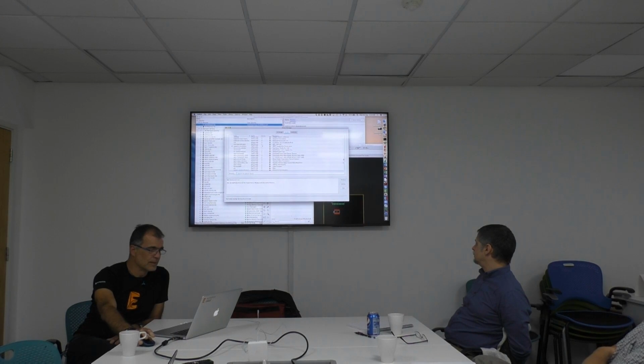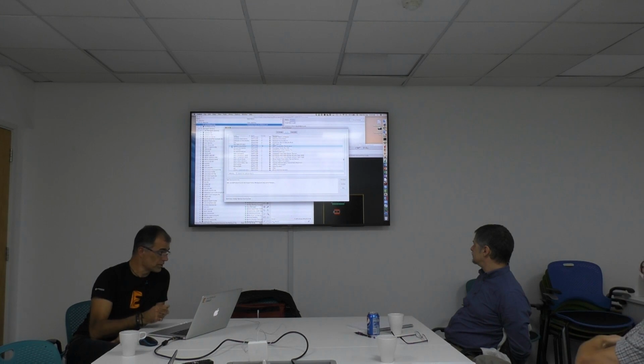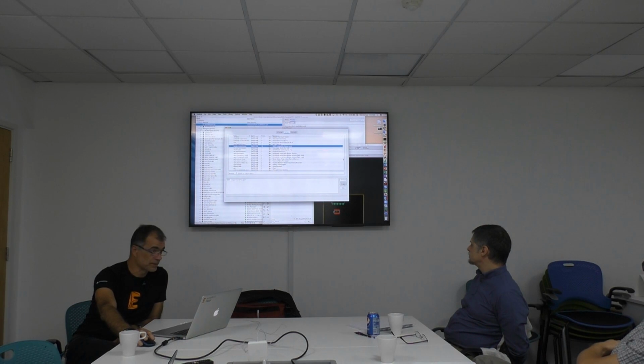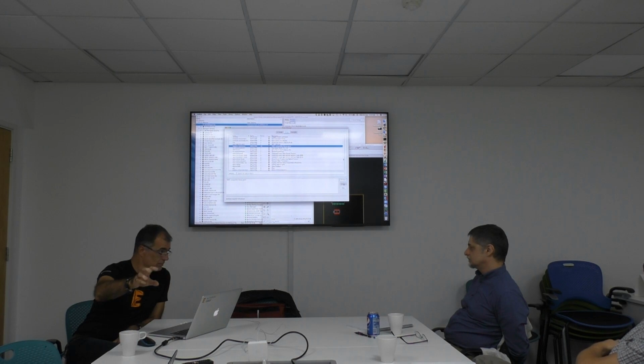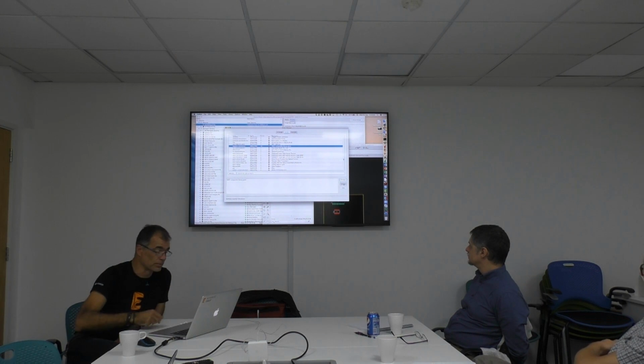There's one. If you get something like this, it would mean there is a newer version available. In this case, it's version 16. I could select it and update it. What happens if I say update? Eagle simply downloads the new library, replaces the old one with the new one, and it's available for you from now in the new version.